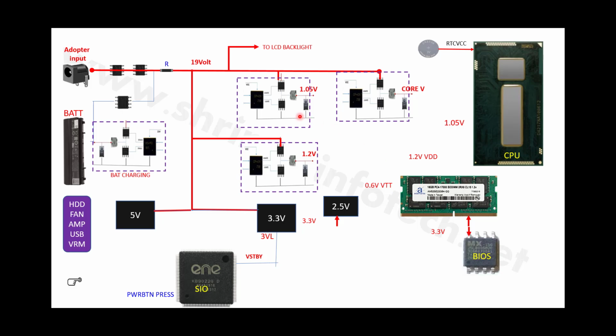We will see everything practically. We have to apply the power from here, and on the DC power supply the current will shoot up. Then what we are going to do is apply current directly at this terminal, at this current sensing resistor, and when the current is limited to 5 amperes, then with the help of a hand we have to observe the motherboard to see which component is getting hot, and that particular component we have to remove.